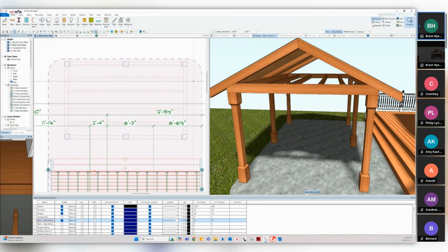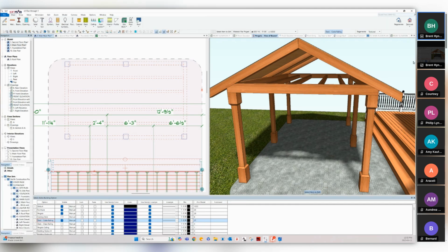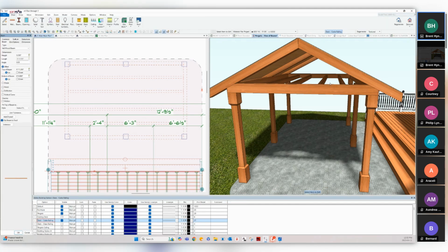Now, what the purpose of this is: when I'm editing the beams, I'll just edit one of these. We've added the option here to fit top of beam to different styles. There are 6 different styles, 3 for roof and 3 for ceiling. They're the same on both, but it's a matter of what we go looking for. So when we're saying fit to roof, it's going to look for the underside of the roof and fit them to that. There was a bit of confusion when we were out in beta and alpha as to what the use of this was, and we had people doing this where their ceiling was flat.